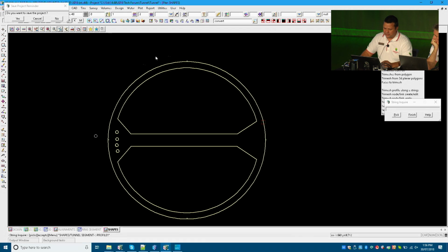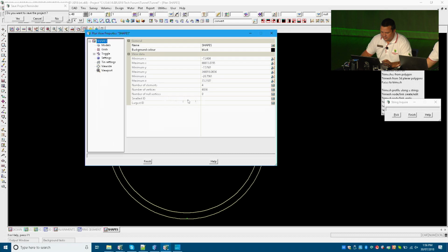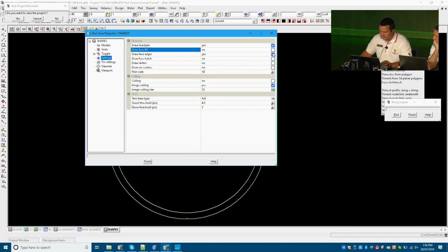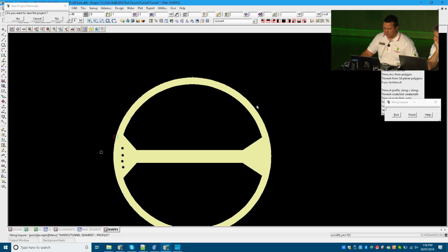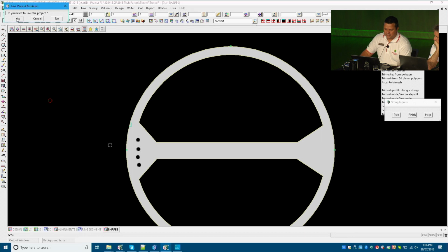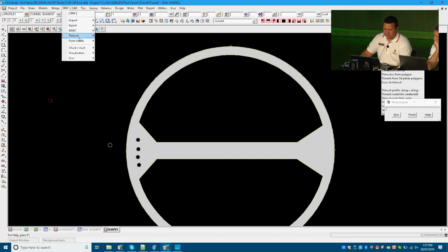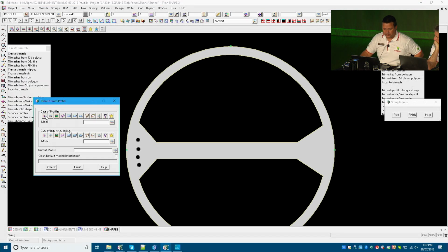So I've got this one string, and if I go back to my settings and say draw the fill there, this is one string with the holes cut in it, just by creating a string, go add hole. Then under BIM again, Trimesh create, we got Trimesh along a profile.